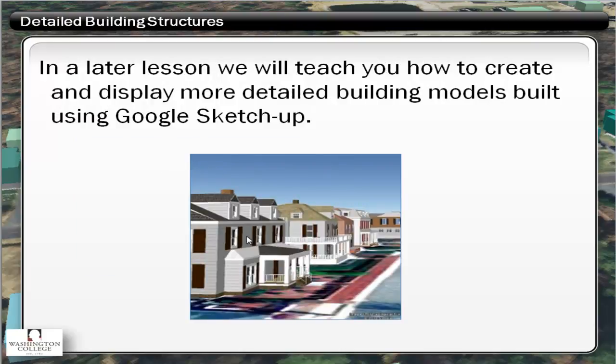ArcScene does have the ability to bring in Google SketchUp buildings. We're going to try to play with that in a later lesson. I will warn you, though, that ArcScene has some capabilities based on your video card capabilities that you're probably unlikely to bring in like hundreds and hundreds of SketchUp buildings unless you make sure that they are well constructed and have a very good design in terms of the number of faces and things like that. It will actually crash ArcScene.